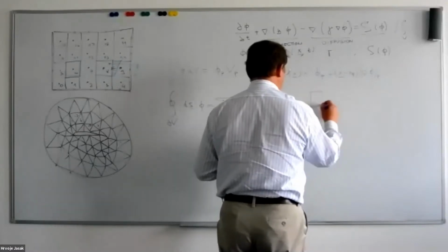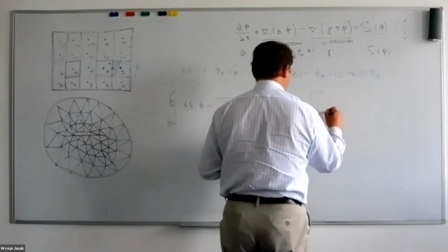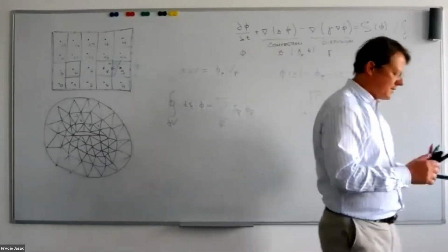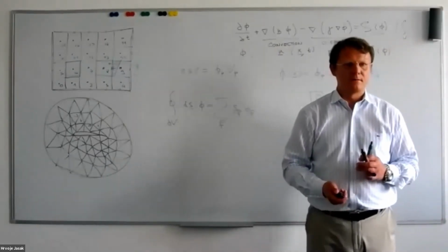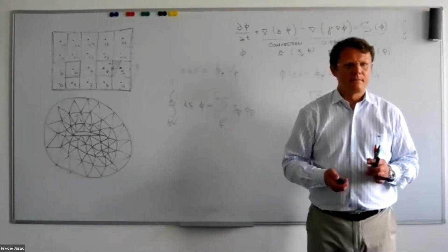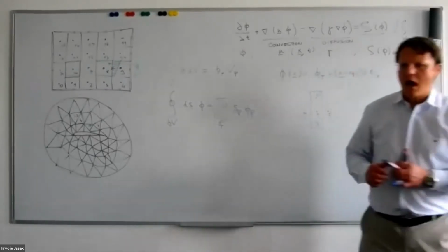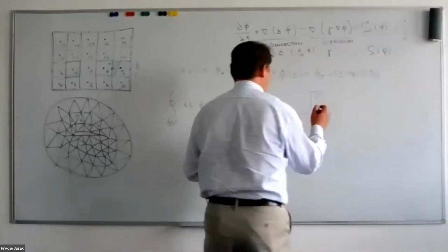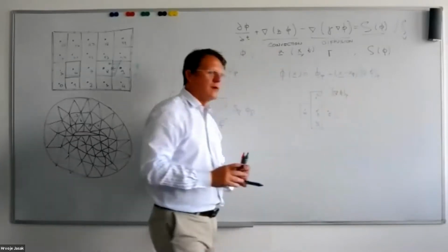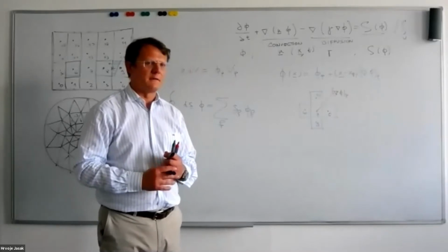Let us consider a stencil in the Cartesian mesh with points marked as I have them on the screen. Considering that you have the values at the cell centers, how would one be able to evaluate grad phi at the location P? The easy solution, of course, says, well, let's use finite differences.